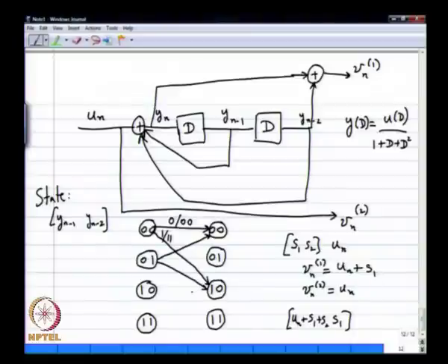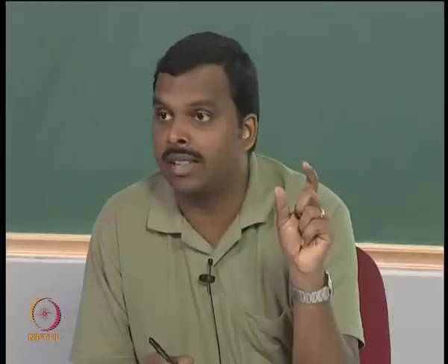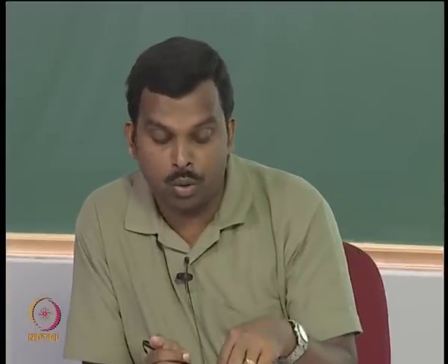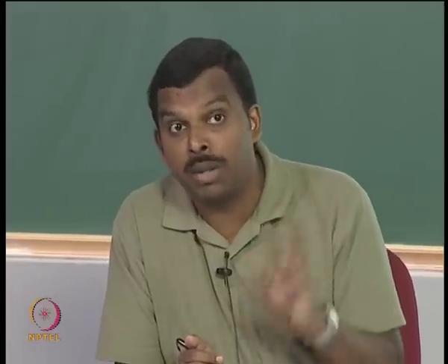Okay, another thing to keep in mind, once again, in a well designed recursive encoder, the inputs coming into a particular state will be different. Okay, in the feed forward case, the inputs going into a particular state will always be the same. You can come to 0 0 only with the 0 input, but in a recursive encoder usually it will be the opposite.